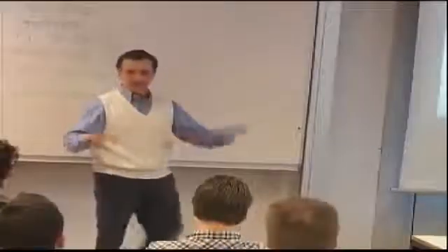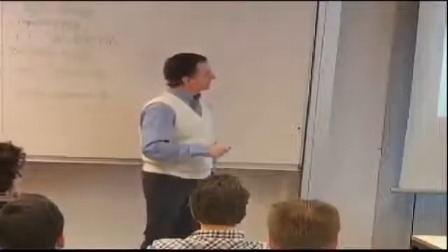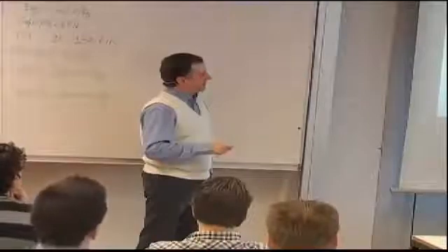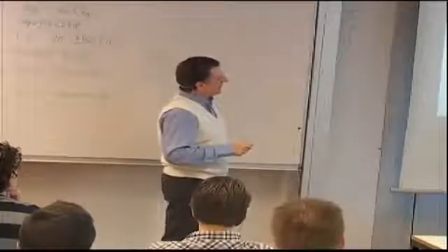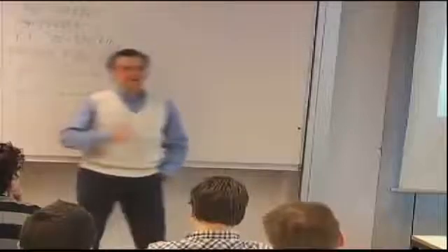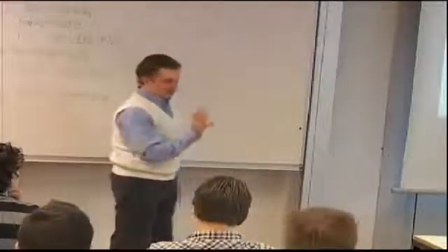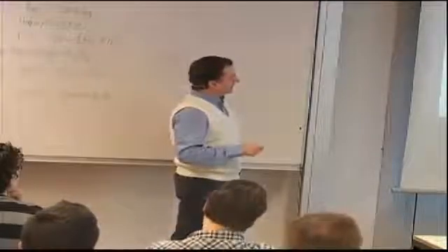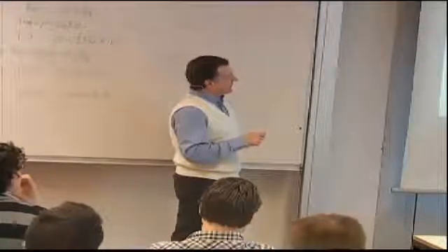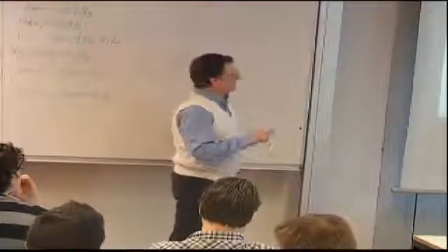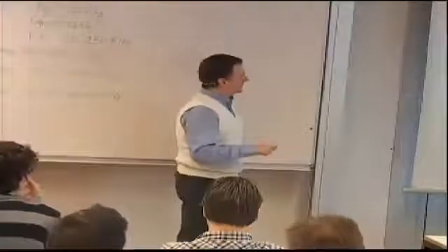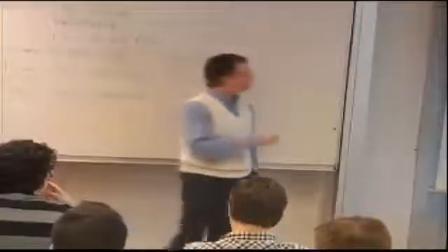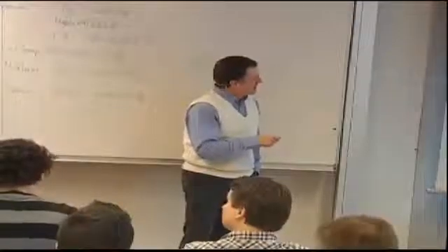So if I take everything together, I will completely destroy this wonderful material that has these excellent properties. Basically, my strength at room temperature ambient and undamaged is somewhere out here, and that's the mean value. Now, I have to reduce this from here to here, 5 to 20%, to account for the worst environmental effects. 5 to 20 depends on the property, depends on the material, depends on the environment you are taking into account. So you're down here, and then you further reduce it to include the worst type of damage. Typically, it's impact damage. And that gives you the mean strength accounting for environment and accounting for damage. And then around that, we have the distribution. We said the material scatter has a certain distribution, and we'll have to go down here to use either the B basis or the A basis design value.